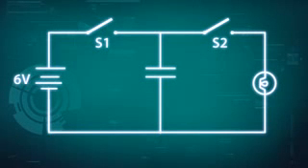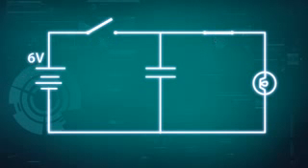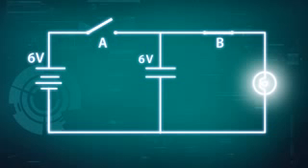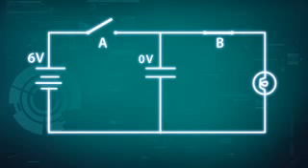Consider this sample circuit. If switch B is turned on, nothing happens to the bulb because the capacitor isn't charged yet. To charge it, we must close switch A. The capacitor, as you have already learned, will charge up. By changing the states of the switches, it now has a load to which it can discharge, and then the bulb glows. But then, notice also that it goes off almost instantly. This happened because the capacitor quickly discharges to the bulb. For a short amount of time, the capacitor acted as a battery.